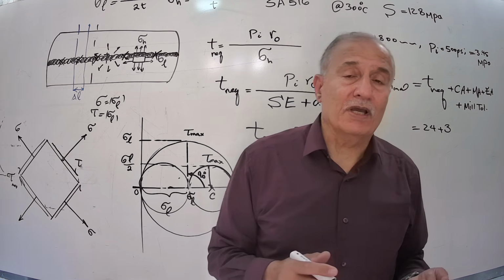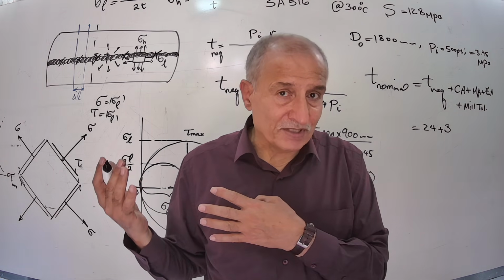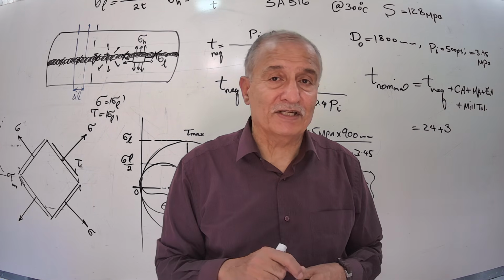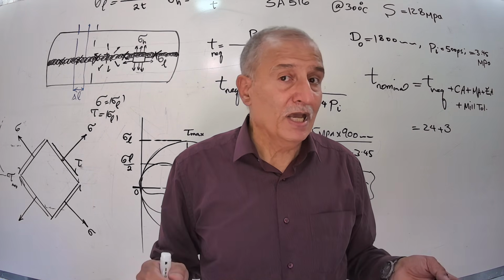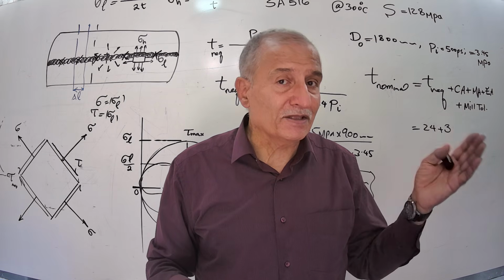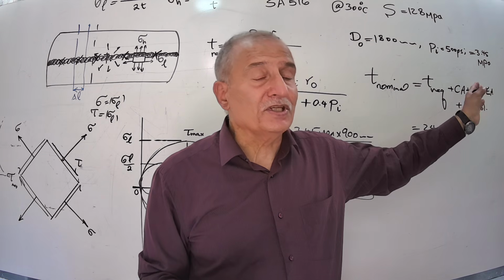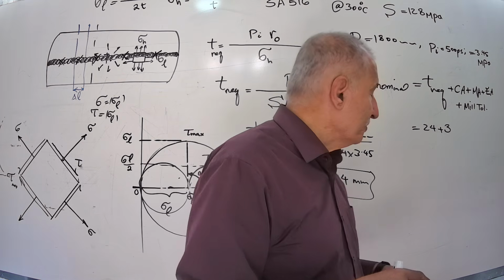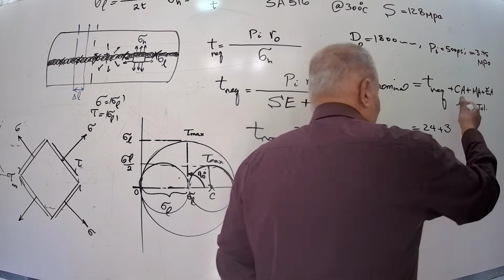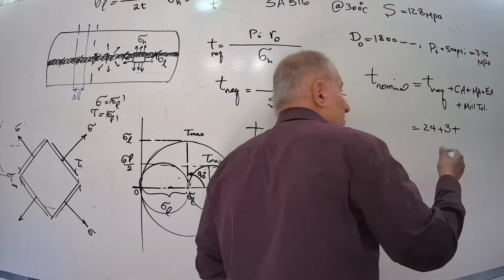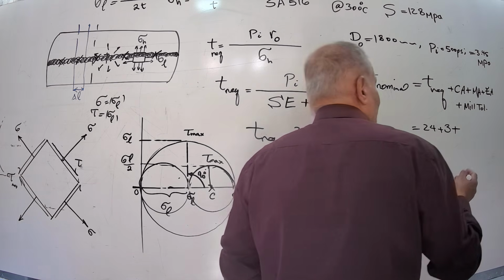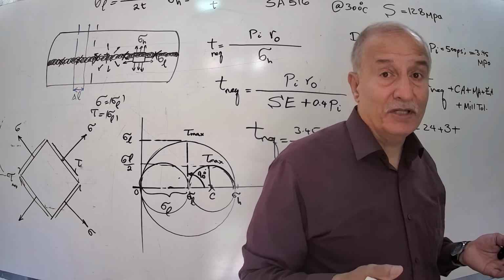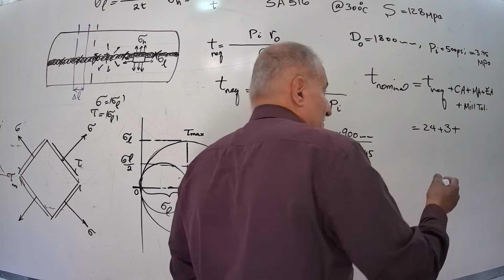If you want the pressure vessel, after fabrication, to have some material removed from its skin, outer shell, or not. If yes, you must add this value to this thickness. How much you are going to remove after fabrication or manufacturing. Here we don't consider anything for that, but maybe 2 or 3 millimeter. Not for this one, but mill tolerance, no, you have to consider it, 12.5%.